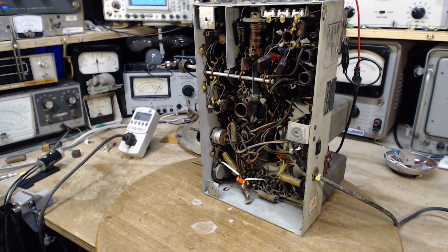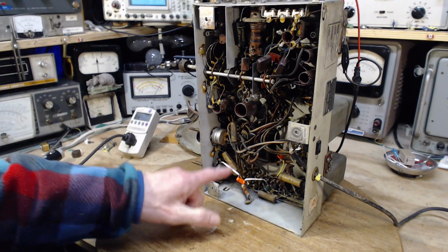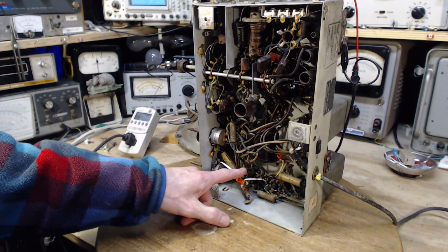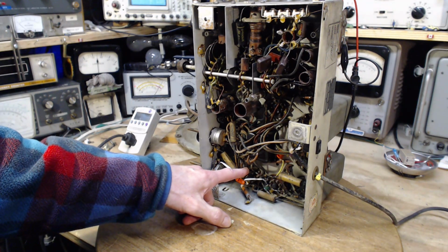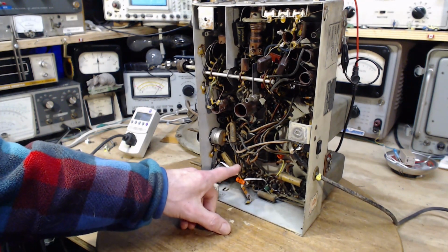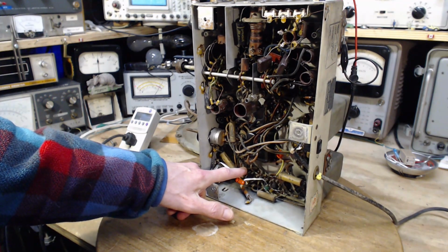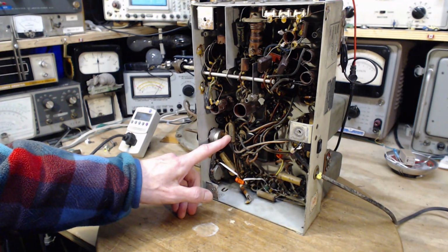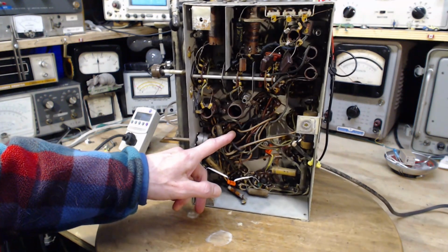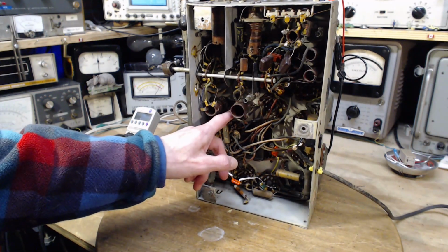Well, as seems to be the case a lot in my shop, things aren't working out here. There should be a capacitor going from pin 3 around to, I believe it was pin 8. There's no capacitor in that position here. There is a capacitor on pin 3. Pin 3 is the plate, and that capacitor is attached to a terminal up here, which is clearly grounded to the chassis.